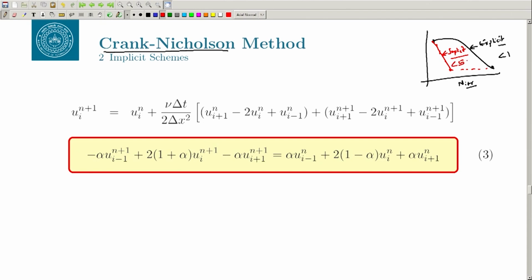So, this is the beauty of the implicit scheme, that it gives you the convergence faster. Of course, if you want to get a time accurate solution at every time step, you should not be using the Courant number very high, otherwise the accuracy with time will go down.